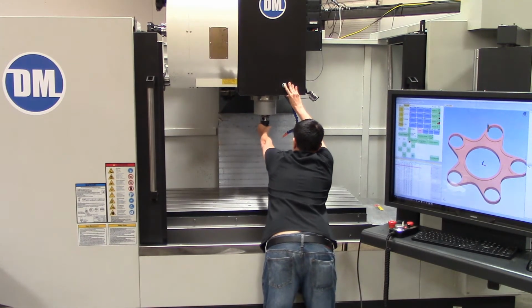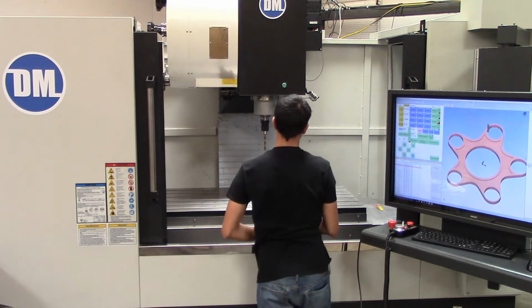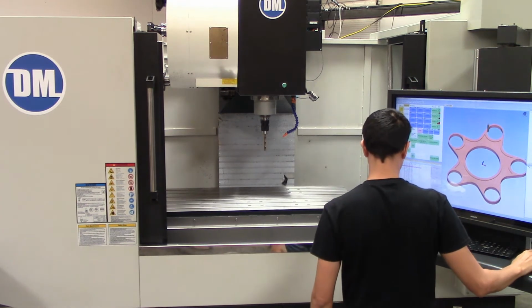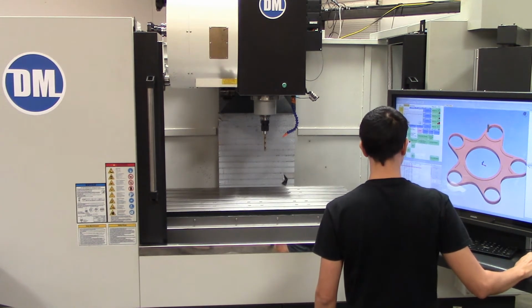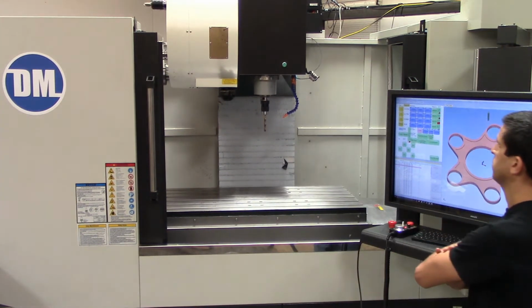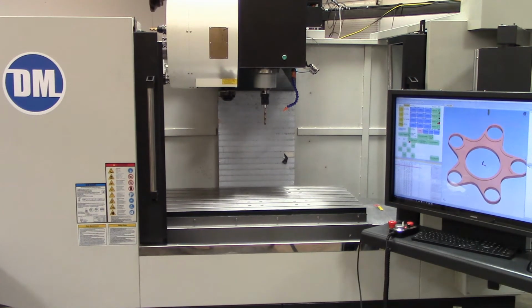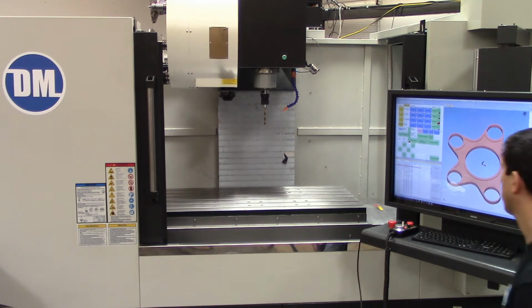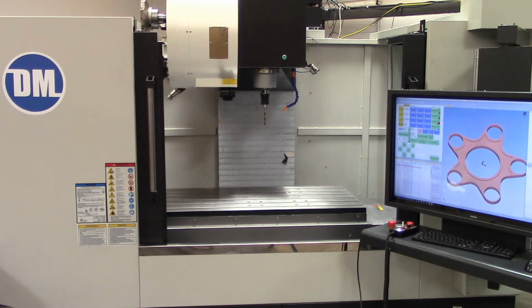And don't let the automatic tool changer scare you. It's easy to operate. Just manually load any tool into the spindle, like this drill chuck. Then select the tool number and press Load Tool into ATC. The machine will then put the drill chuck away in the selected pocket. Anytime you want to use the drill, just select it from the list and press Set Active, or run a program that uses the drill. Here I'll tell it to set active the center drill that I had previously loaded.